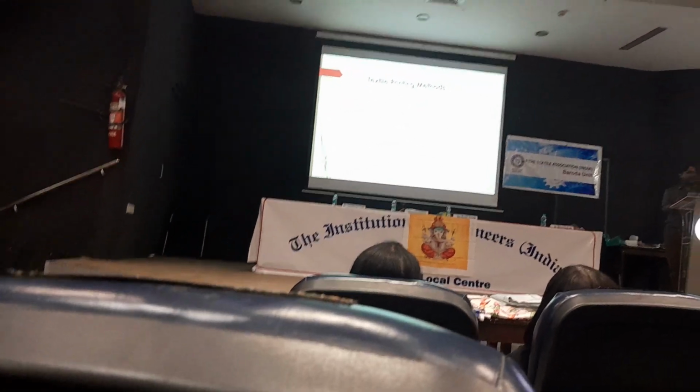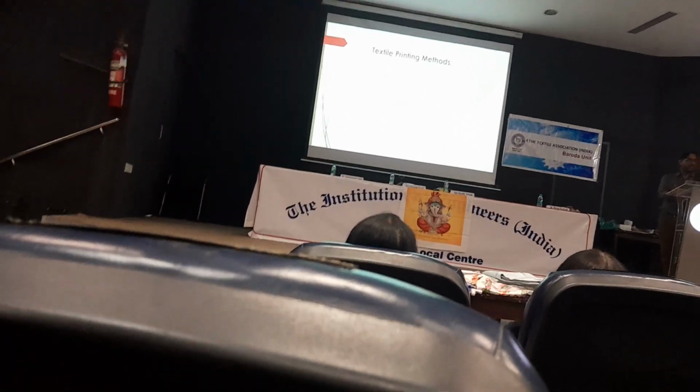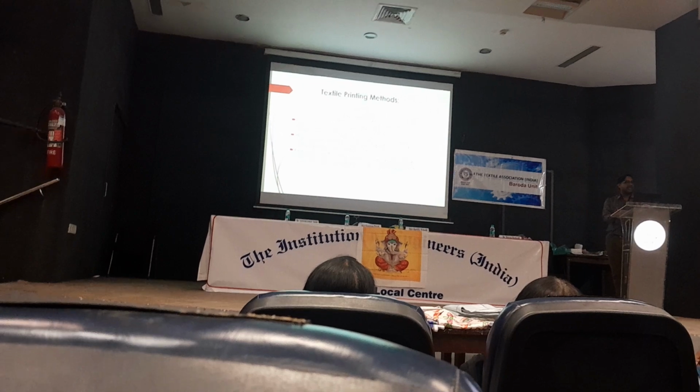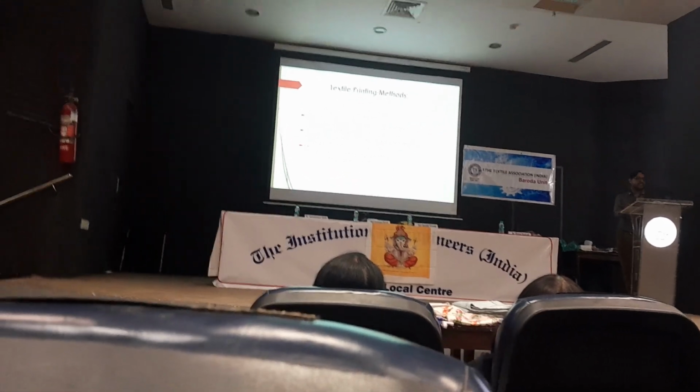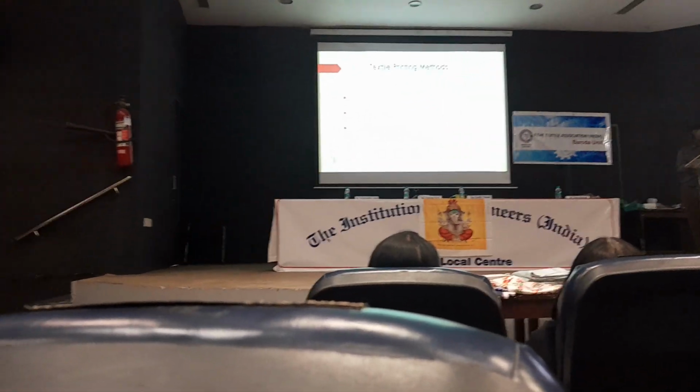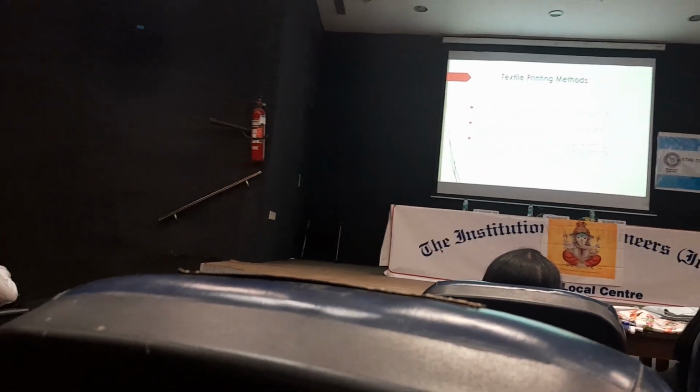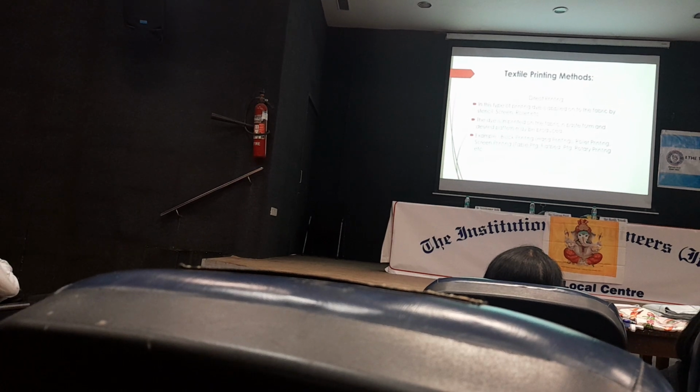First, direct printing, resist printing, discharge printing. So what is direct printing? Direct printing is where dyes are applied on the fabric by stencils, screens, rollers, etc. The dye is applied on the fabric as a paste form, and a desired pattern may be produced.